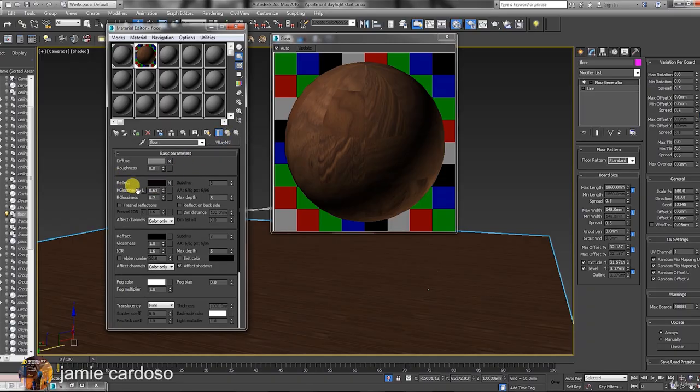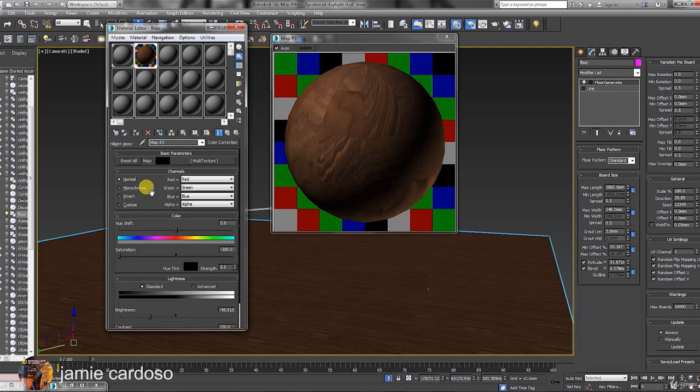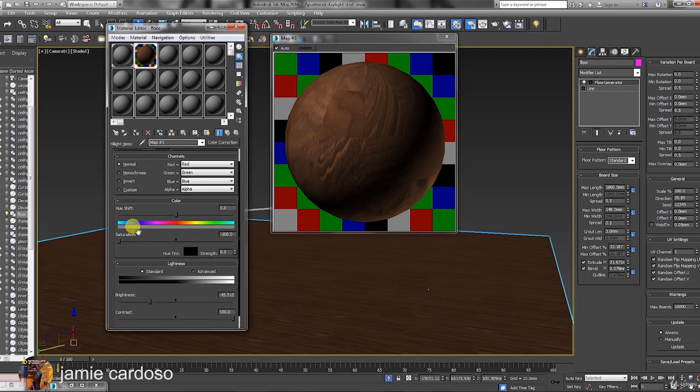The next step is to copy the contents from the Reflect toggle into the Highlight Glossiness toggle. Just drag and drop it there. Choose the option to copy. Go inside the Highlight Glossiness toggle. Set the brightness value to about 85.382 and the contrast value to about 22.259.